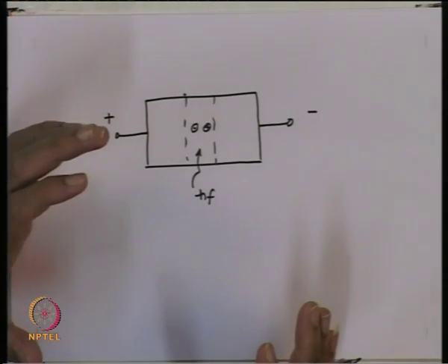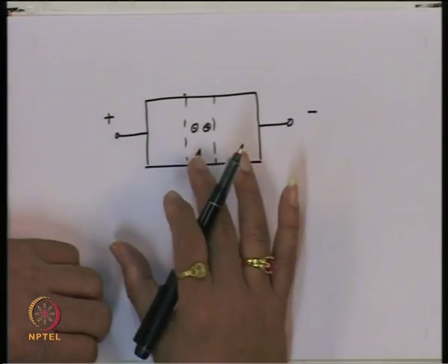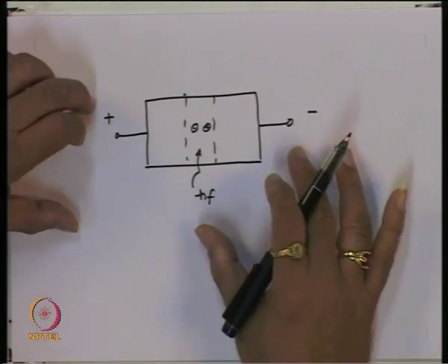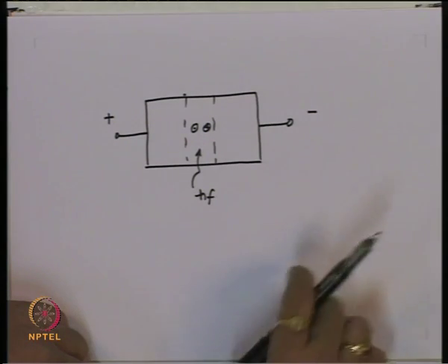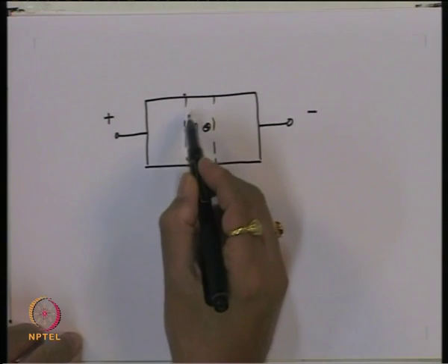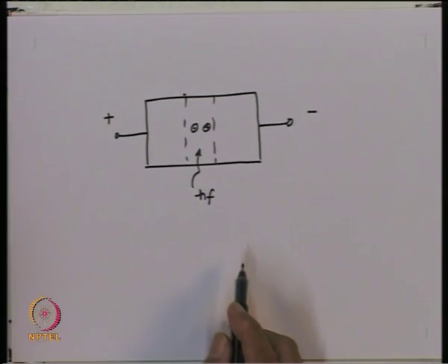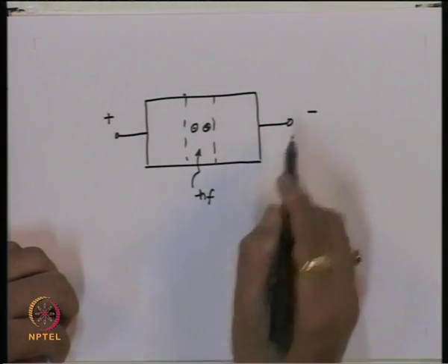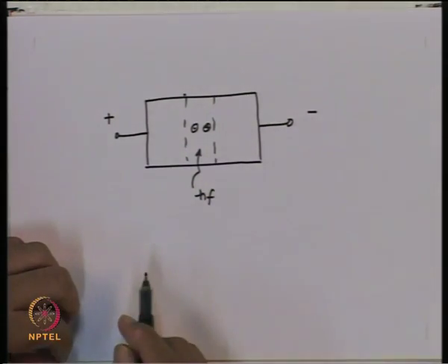in which, in the ideal situation, in the absence of the electron hole pair generated due to the photon, the current flow will be 0. Of course, in practice, because of thermal excitation, we also have electron hole pairs generated, and we get what is called the reverse saturation current inside the PN junction.